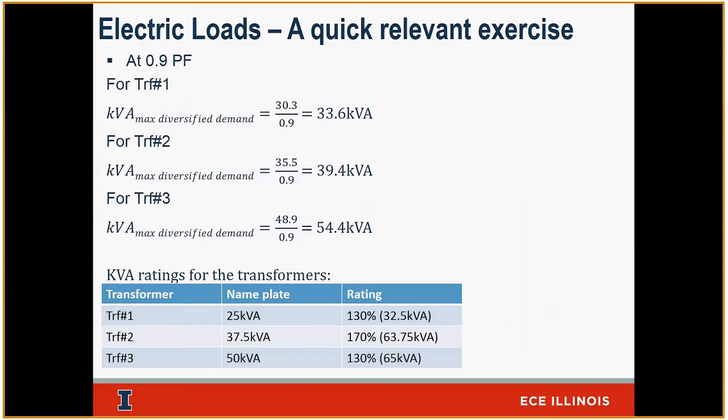Doesn't it also depend on the amount of time you're operating it at 130%? Like, you won't operate it at 130% for the lifetime of the asset. Yeah. So that's what we're saying. At 130% and above, so equal to or above, you start losing life on the asset. As long as you're below the 130% threshold, you are fine. You can operate it for 15 years.